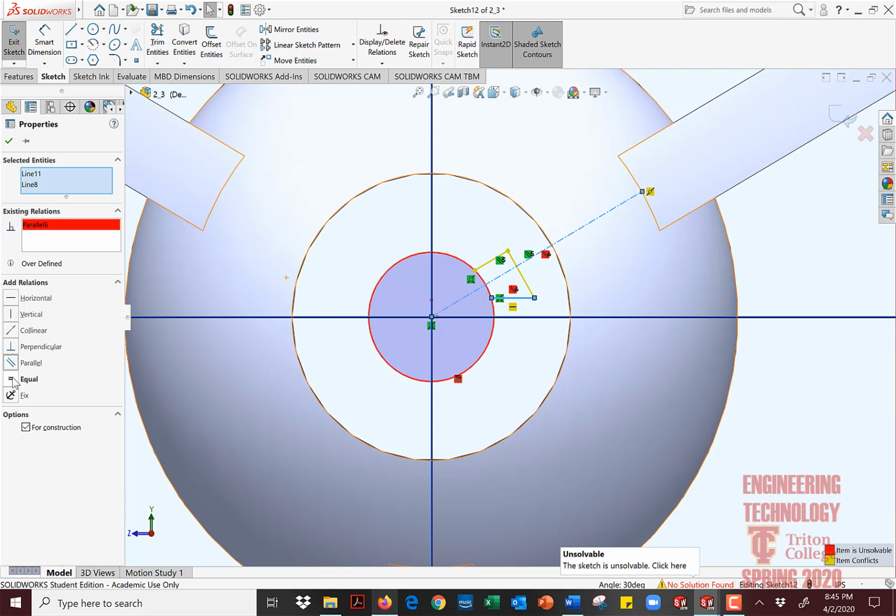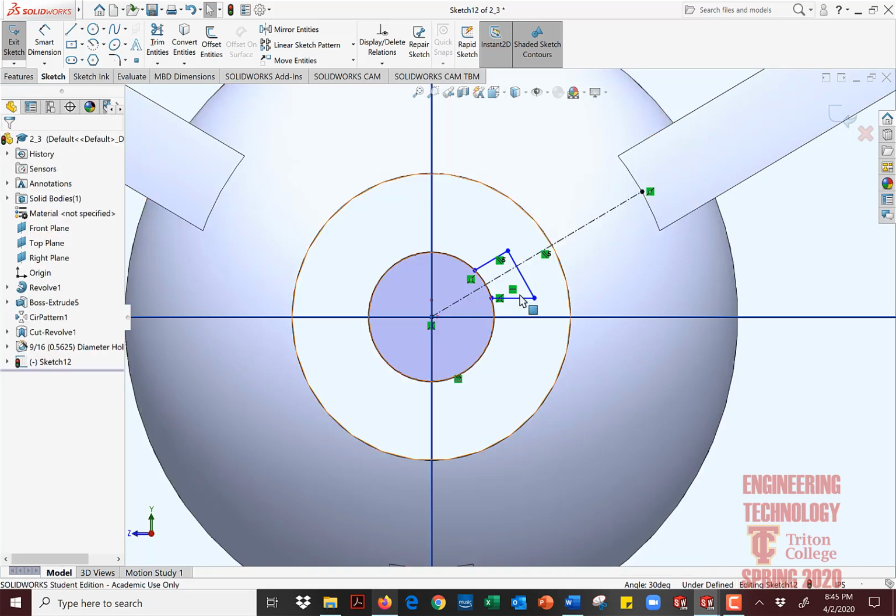So why won't it let me do that? See how it says parallel is fighting it? See that? So I have to click up here and delete it. Okay, now it's not fighting it anymore. So why is it fighting it? When you look at this, it's got two constraints on it already. One is a point coincident, and the other one is called horizontal. So I already made a constraint, not intentionally, but the way I moved my mouse, it automatically assumed where I wanted to put it.